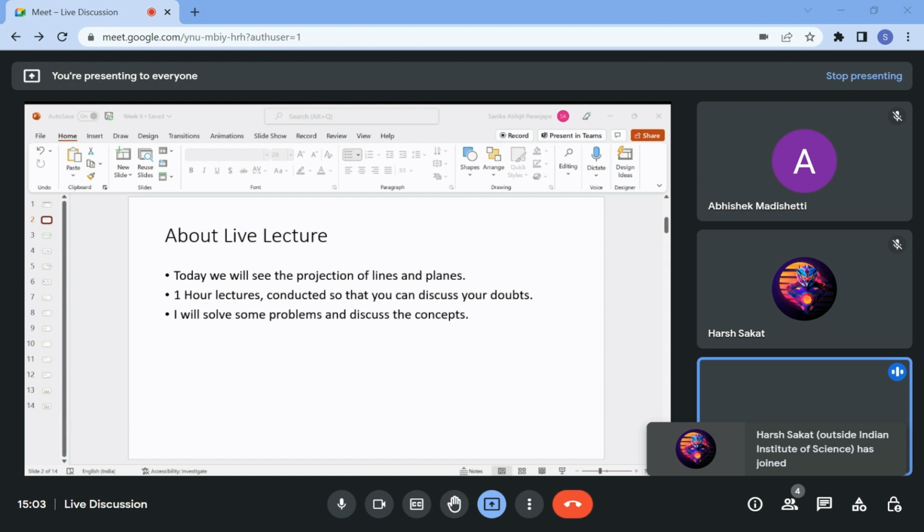I have fixed point A here, and the line makes an angle of 30 degrees with the horizontal plane. The angle with the horizontal plane is always seen in the vertical plane. Now as I move along this arrow in the anti-clockwise direction, my B point will go here, come back here, go here, and come back here.